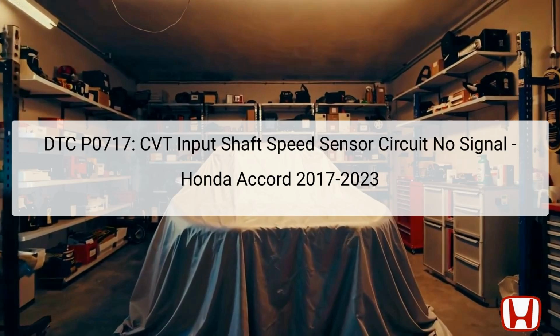DTC P0717 indicates a problem in the continuous variable transmission, CVT, related to the input shaft speed sensor A circuit. The input shaft speed sensor is responsible for monitoring the speed of the input shaft in the CVT. This data is crucial for ensuring optimal performance and smooth operation of the transmission. The sensor is located within the transmission assembly, making it somewhat challenging to access without proper tools.